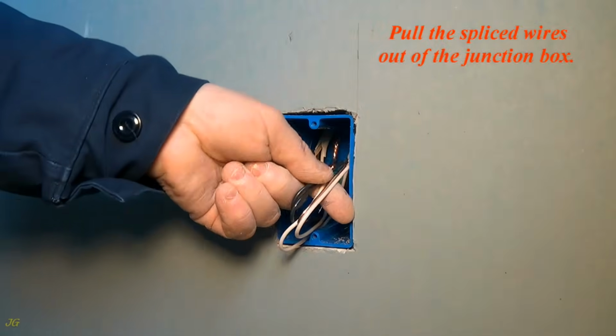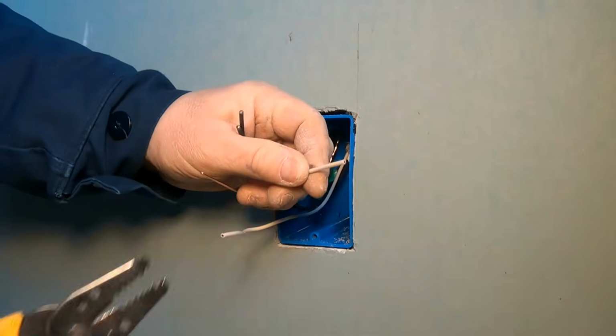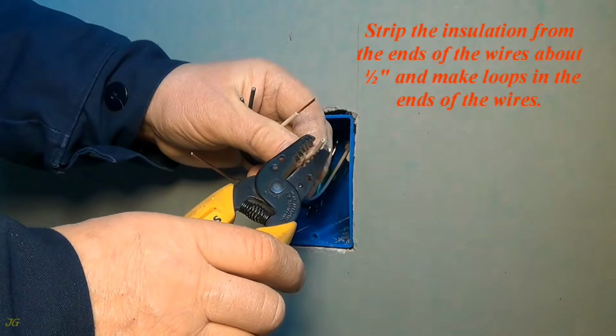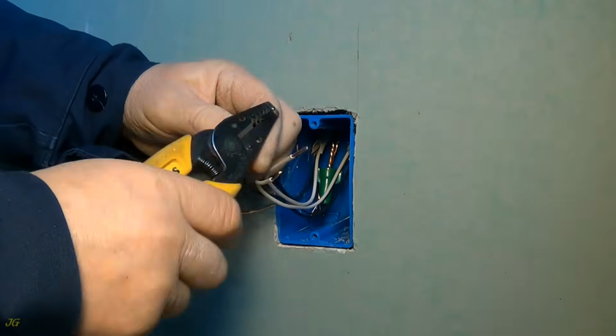Pull the spliced wires out of the junction box. Strip the insulation from the ends of the wires about 1/2 inch and make loops in the ends of the wires.